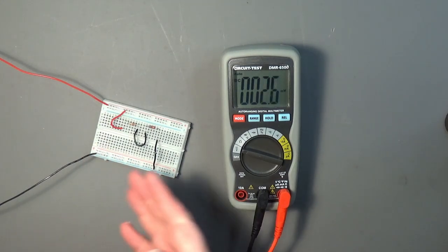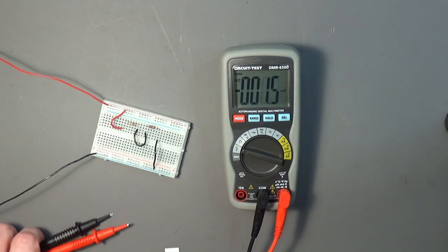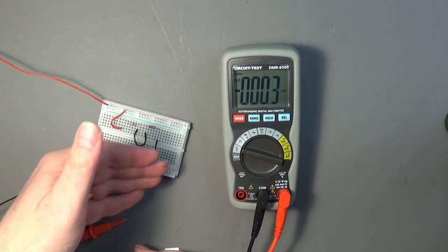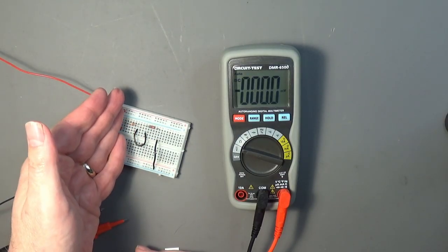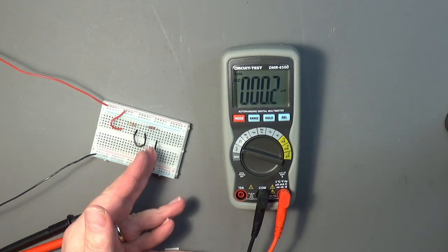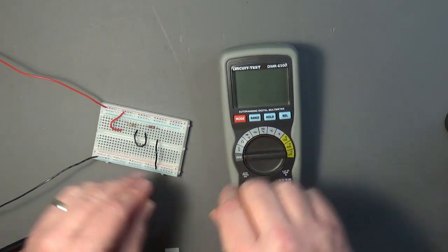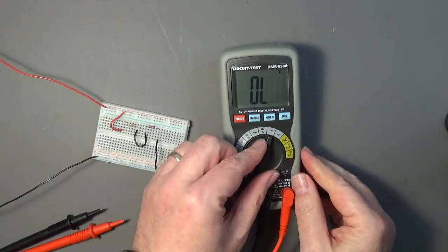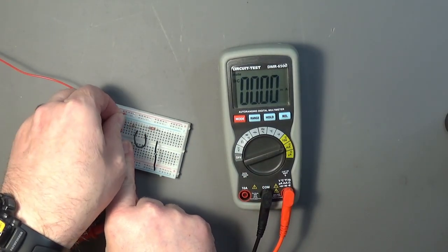Now, in this circuit, the resistance is of course fixed, but what about the current? So we have a current coming into the circuit and out, and it's flowing also in between. So is the current here different from the current here, different from the current here? Well, let's find that out. So what we'll do is we'll switch our meter over to milliamps, and we'll start with what the current going in is.